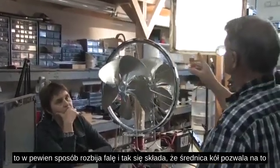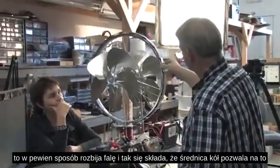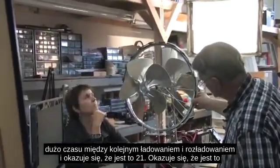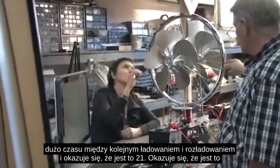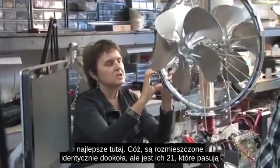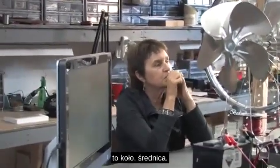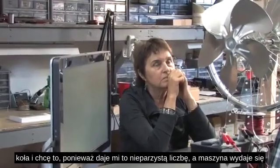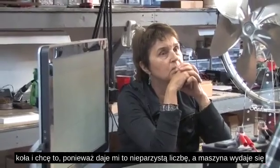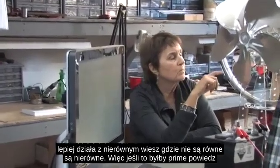And it so happens that the wheel's diameter allows you this much time between the next charge and discharge. And it happens to be 21. It works out to be the best here. They're spaced identically all the way around, but there's 21 of them that fit this wheel, the diameter of the wheel. And I want that because that gives me an uneven number. And the machine seems to work better when they're not even, they're uneven.